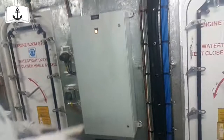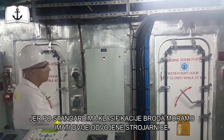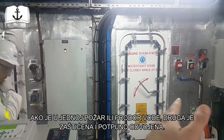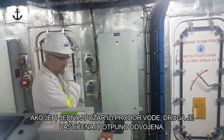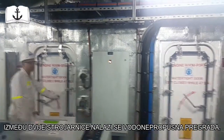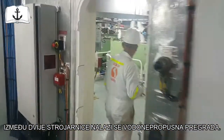Okay, so you showed that we have two engine rooms. Why separate? Because according to the dynamic positioning class DP2, we should have two separate engine rooms. So DP2 vessels need to have segregated engine rooms. In case this one has a fire or flooding, it's not working. Or pirates. Yes. The other one is going to keep going. This is what we said about redundancy. Exactly. Just like you have redundancy there, you need to have it everywhere. So the engine room is completely segregated. There's a wall over there, and a watertight door between. Okay, let's go to the white part of the engine room now.